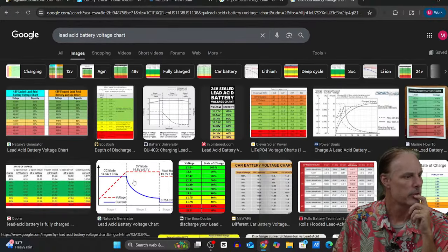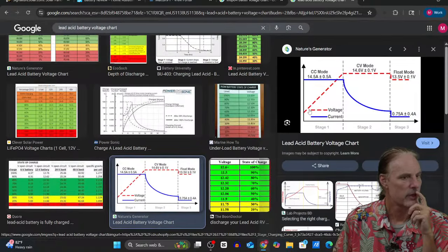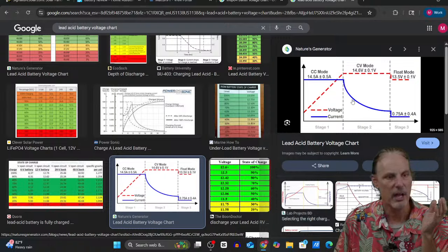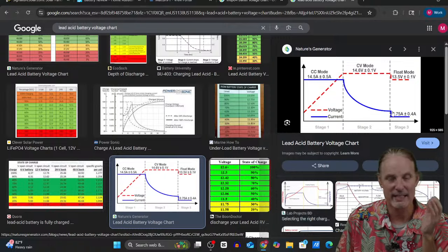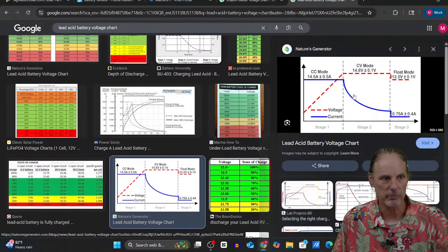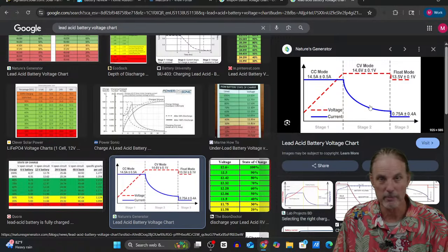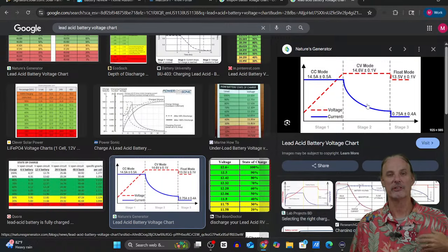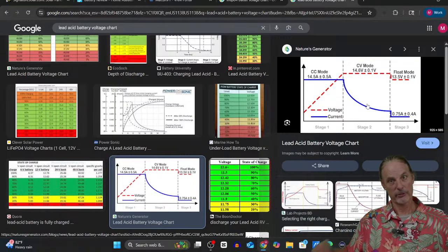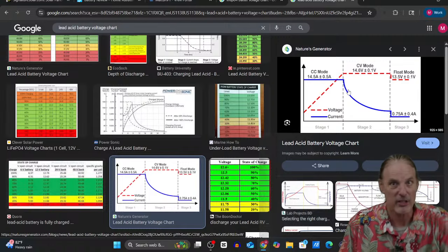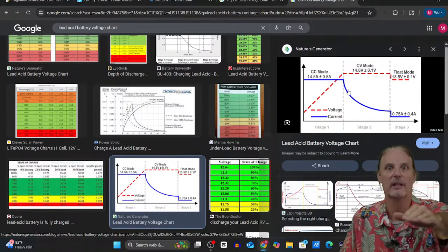Oh, there we go. So you can see here that this starts off at 14.5, but the entire life of the battery, it is dragging down to where it gets to the bottom. So you can easily go in and say, well, at this point, my battery is at this state of charge, and at this point, my battery is at this state of charge. And that is why you'll see in a lot of these devices where you have these lithium drop-ins, where the state of charge is useless afterwards, because the lithium battery gets to this 3.2 range here in the middle and then just stays for 80% of the life of the battery.